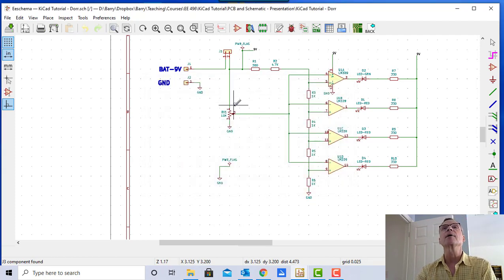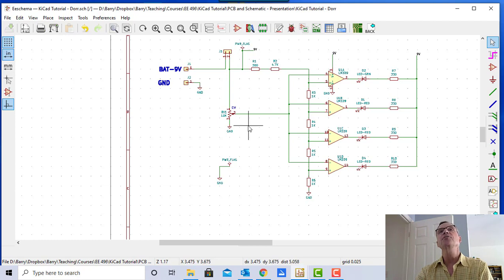I do this on all my schematics because what this tells me is that if I turn the potentiometer fully clockwise, pin 2 is going to be connected to pin 1. So when I pick my footprint, I need to make sure that that is indeed what that potentiometer actually does.